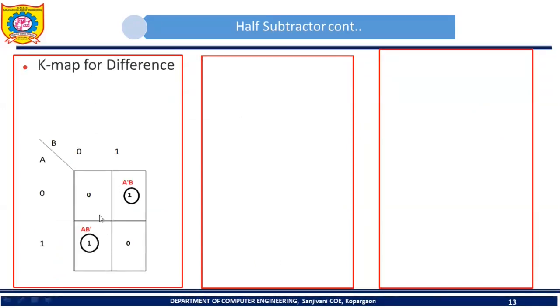So first of all, let's try to draw K-map for difference. So K-map for difference will be like this. In this K-map, grouping of 2 ones is not possible. These 2 ones are not adjacent to each other. So that's why we have to make group of these isolated 1s. So here we have 2 groups. After making the group, what is the next step? We have to write product term corresponding to each group. So for this group, what is the value of A? A is 0, so that's why A prime. What is value of B? B is 1, so that's why B. So A prime B is the term corresponding to this one.